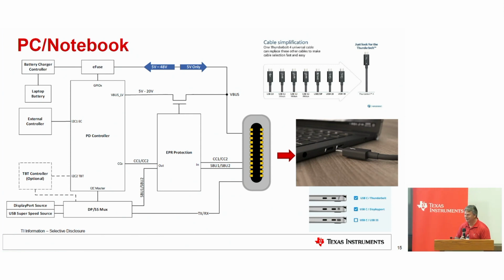Oh, there's a lot of questions there. I'll handle them in the order that I know the answers. Anytime you want to put the USB logo on, you have to go through compliance, because you need to guarantee and show that you comply with the USB spec. Even if you're PD, you have to go through those compliance specs. Then you can put the USB compliant logo, and you're guaranteeing that with whatever devices you connect, you can use all the off-the-shelf cables, and everything will work together.